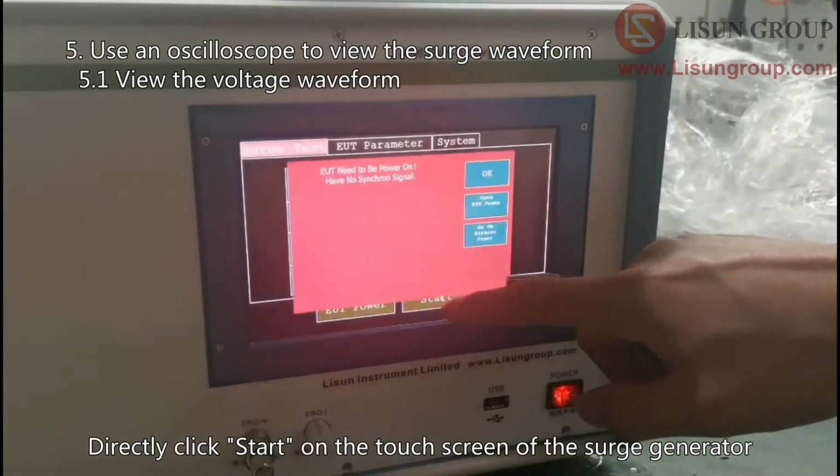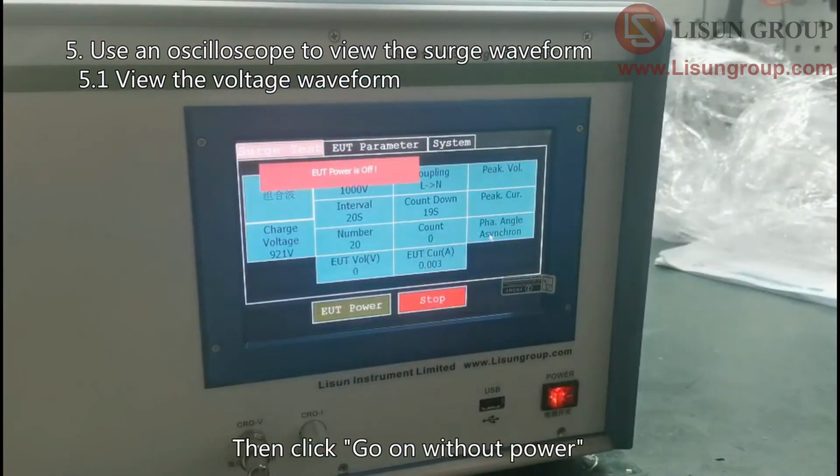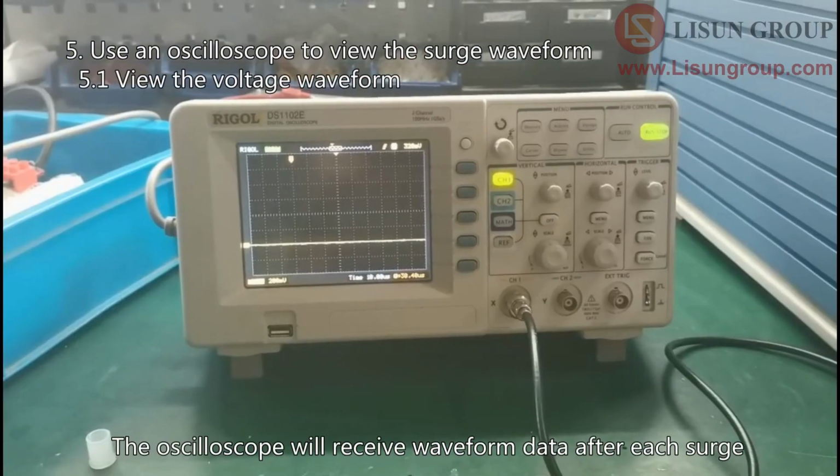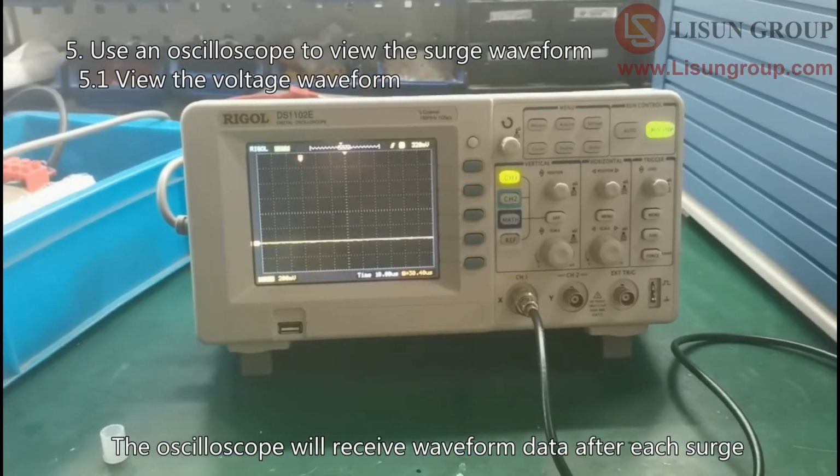Directly click Start on the touch screen of the surge generator. Then click Go on without power. The oscilloscope will receive waveform data after each surge.